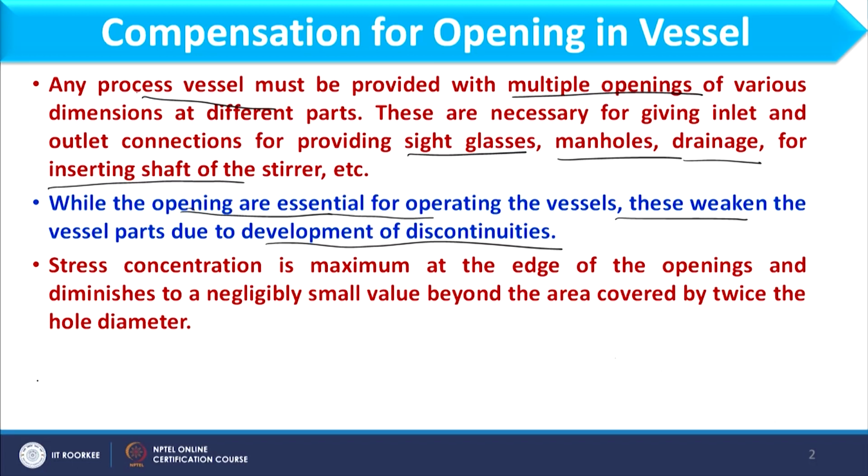So, stress concentration is maximum at the edge of the opening and diminishes to a negligibly small value beyond the area covered by twice the hole diameter. Okay. What is the meaning of this? Let us take the example of that cloth. When I have a hole over here and I put a certain force into this, what will happen? It will start tearing from this. Why will it start tearing from this? Because stress is maximum at the edge of this opening, and experience says that this stress diminishes after twice the diameter of the opening.